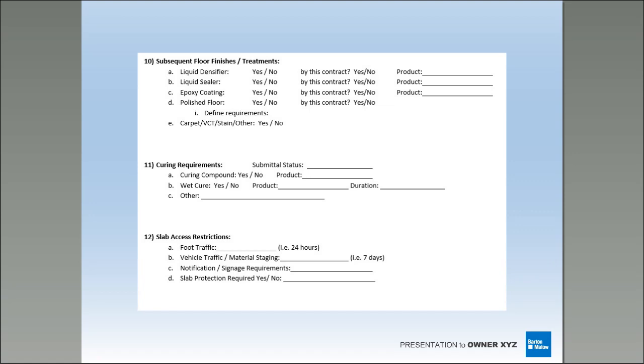Curing requirements. As a polisher, I guarantee you I'm probably not going to want to see a curing compound. I'm typically going to want to see a wet cure. But you're going to want to know the duration, how long it's going to be down. Are the people putting it down qualified? Have they used it before? What's their success rate? You want some comfort level with that, right?